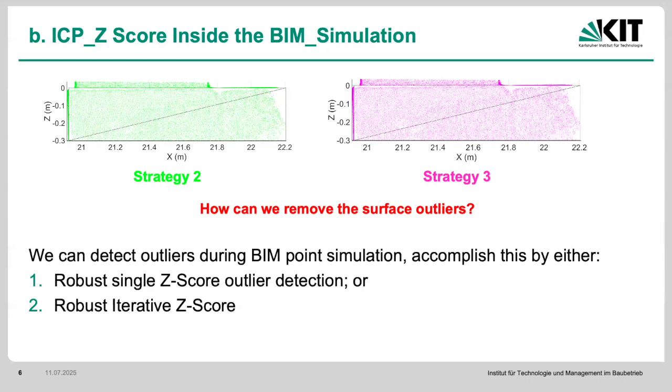Sometimes you might say, okay, when the RMSE between 2 iterations is less than a hundredths of a millimeter, well, we're not going to get, in an engineering sense, significantly better results. Therefore, we would stop it there. So you can also justify it, especially if you're using metric scales. You could justify that, and more or less the order and magnitude of the error associated with your instrument. So for instance, if it's a laser scanner, it's within millimeters, right? So if the accuracy between the estimation of 2, let's say, iterations is less than 2 orders of magnitude compared to that, that definitely, in an engineering and applied sense, would be sufficient enough for us, right?